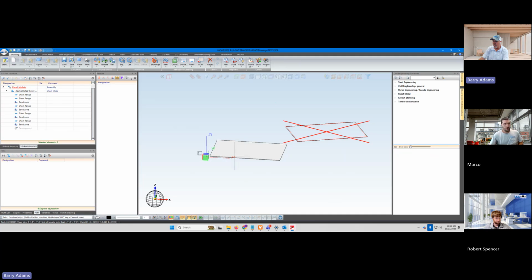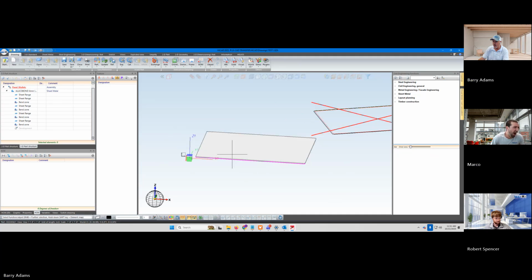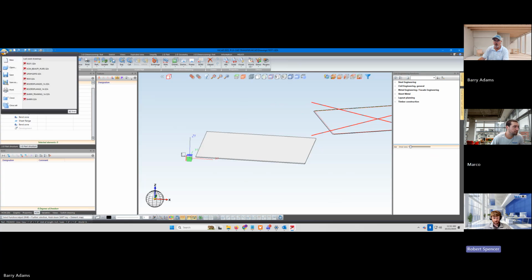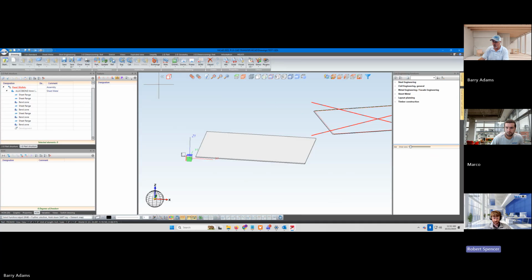Probably this one right here, I think. I thought we got rid of that. Well, maybe I didn't save it. You saved it to your catalog, right? Pretty sure. Oh yeah. Okay, we can retrieve it. So if you saved it to your library but forgot to save the actual SCA drawing file, we can dig it out of the catalog directories and import it right back in, and then you can save it as a drawing again. Okay. So let's try that.